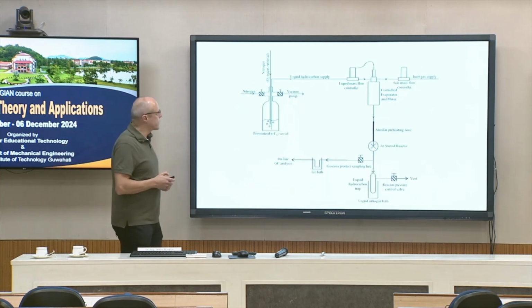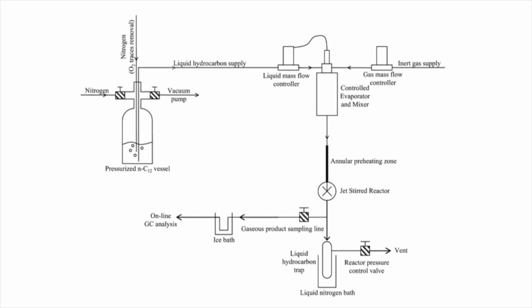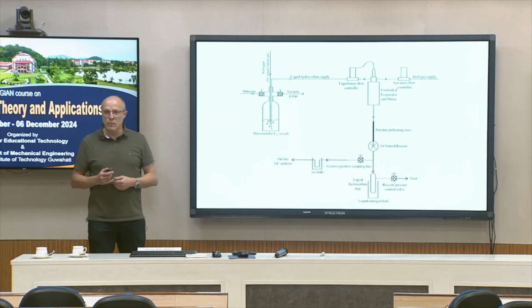This is also for liquid hydrocarbons. Of course, you need a controlled evaporator and mixer here. But nevertheless, this could be done. And here in this example, they used a gas chromatograph to analyze the mixture composition of the outflow.